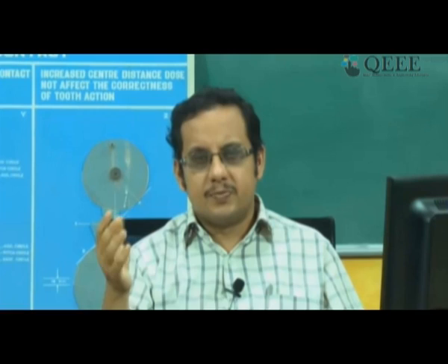Okay, the last question that I have is, which profile has the least pressure angle? See, we are talking about involute tooth profile. Involute tooth profiles can be made with pressure angle 14.5 degree, 20 degree, or 25 degree. We are not actually comparing different tooth profiles at this stage. In fact, as I told you, it's difficult to make that comparison because pressure angle is not constant for other tooth profiles. Pressure angle happens to be constant for involute tooth profile, and the standard pressure angles in which mass produced gears appear are 14.5, 20 degree and 25 degree.